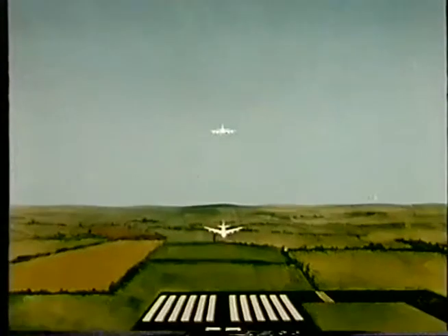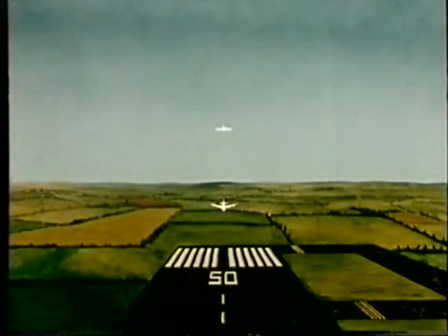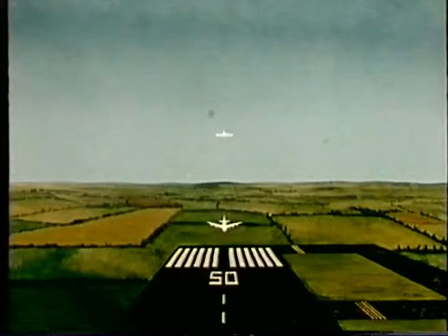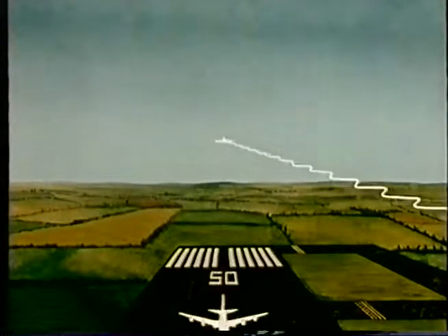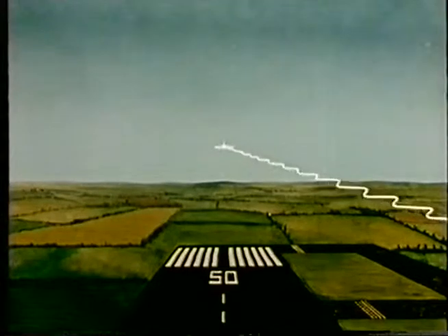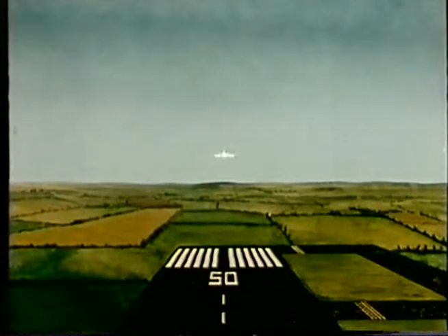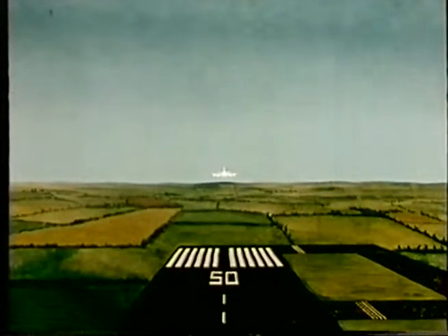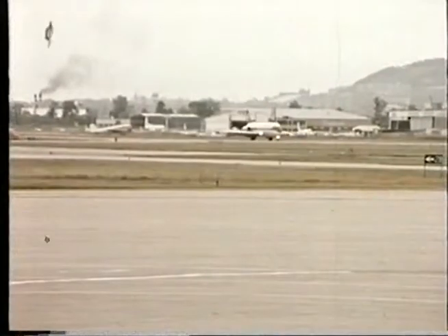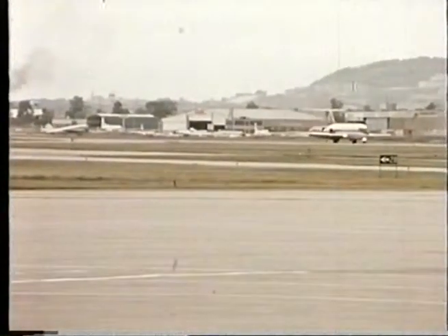An aircraft may be cleared to land where there is reasonable assurance that separation will exist when the aircraft crosses the runway threshold, but a clearance to land shall not be issued until a preceding landing aircraft has crossed the runway threshold. Lower separation than these, and the minima specified for takeoff, may be prescribed by the appropriate ATS authority after consultation with operators, taking into account such factors as runway length, aerodrome layout, and type of aircraft involved.